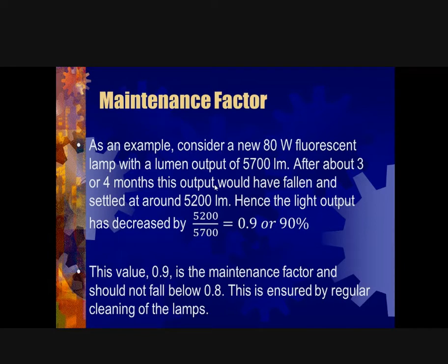It's very important to know, in terms of maintenance engineering, right? So for instance, you start a little company and you get a building to maintain as a contract, you need to ensure that your diffusers become a part of the maintenance process. Similar to your AC, you want to clean your AC filters because you want the AC to work as efficiently as designed, as can be. So same thing with the light. You want your maintenance factor to be the best it can be, right?